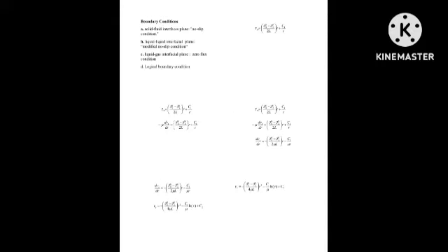This simplification arises because under steady, fully developed and axisymmetrical conditions, the velocity components in the radial Vr and angular V theta directions are 0, and there are no variations in the angular and axial directions. To solve this differential equation for Vz of r, we integrate it twice with respect to r, introducing two constants of integration. Applying the no-slip boundary conditions at r equal to ri, Vz equal to 0, and at r equal to ro, Vz equal to 0, we can solve for these constants.